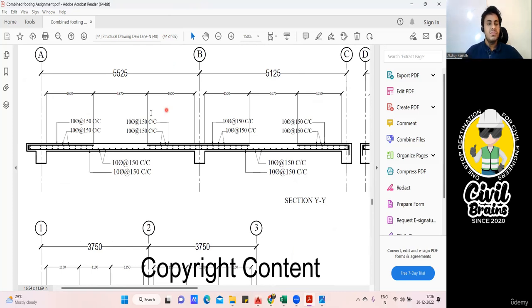Yes, it is ABC. So this is A, this is B, and this is C. I want to find this. I want to know the length from here to here, from the face of the beam. It is directly given as 1650. Simple. And after that, this part will go in the beam minus cover, and then it is given as L. In this drawing, some may get confused.